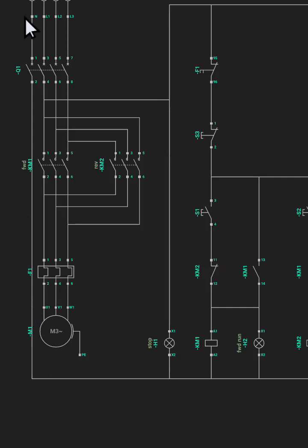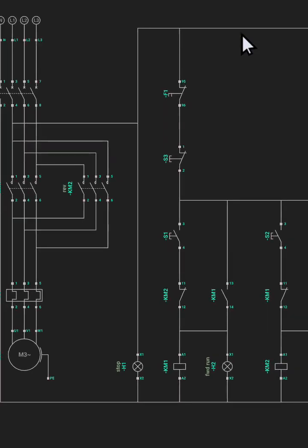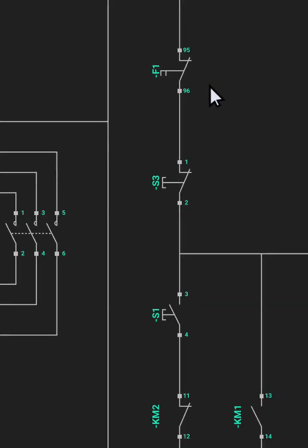Alright, so the first place the power cable enters is the normally closed terminal of the overload. You know why it is like that? So that whenever the motor trips, this place becomes open, deactivating the control network, meaning that the motor will not move, it will stop. You know, it's the control operation that controls the power section.